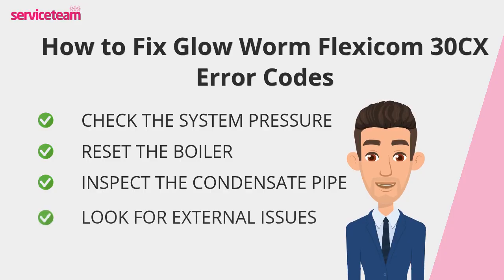If the fault is still showing, check a few basics around the system. Make sure your gas supply is on and other gas appliances are working. Confirm the boiler has power, check your thermostat settings, and look at the flue terminal outside to make sure nothing is blocking it. Also, inspect your pipework for any visible leaks. These simple checks can often reveal the cause of the issue.